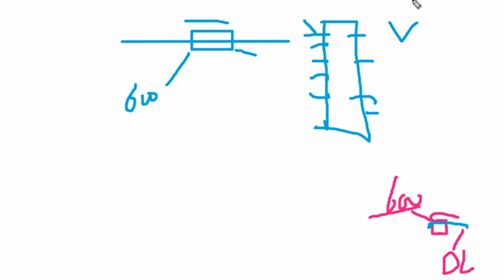Now, in some cases, when you connect a jumper from here to here, from this end to this end, but when you measure the diode mode value, it is still open. OL. Why did this happen?